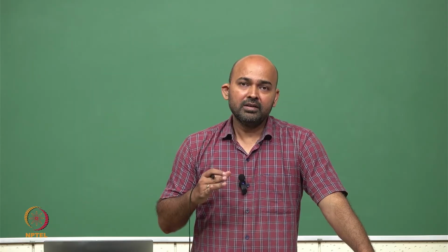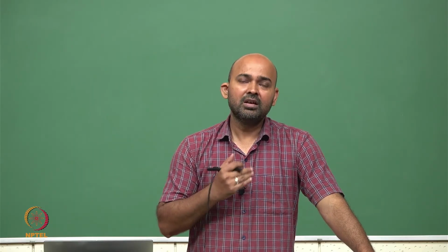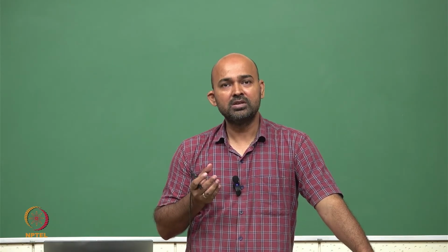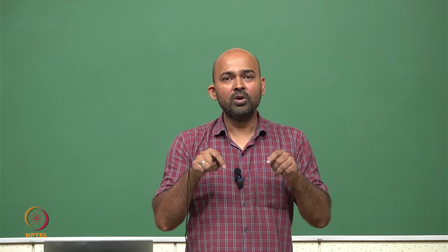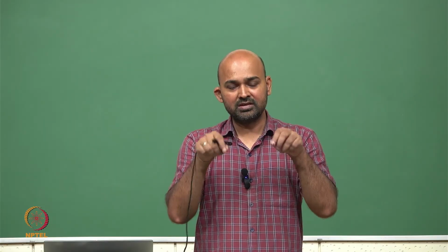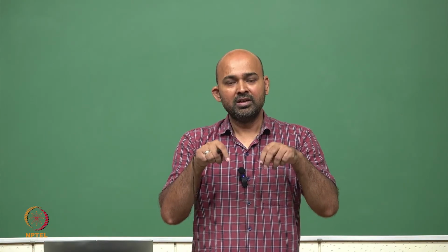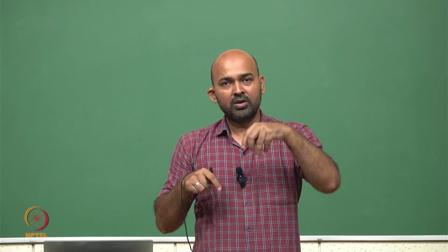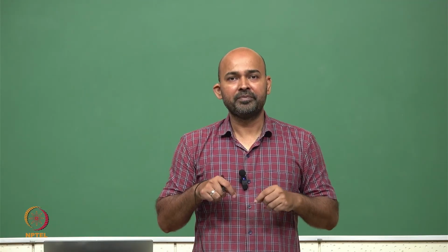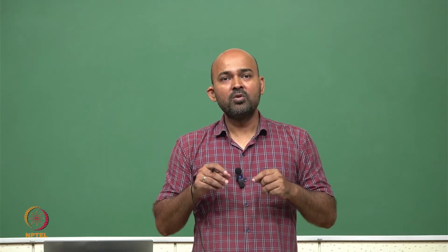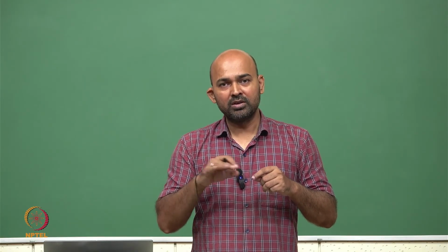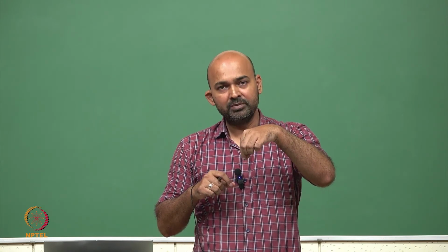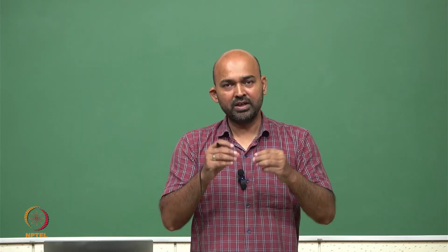And there are two technologies as we earlier discussed. One is through hole technology, one is the surface mount technology, where in the through hole technology we had this resistor which has two lead wires. We have to dig the hole or put PTH, plated through hole, on the substrate to put them in place. In surface mount technology, we need not put the holes, we just have landing pads. On them we put our component, heat it up so that it gets connected.